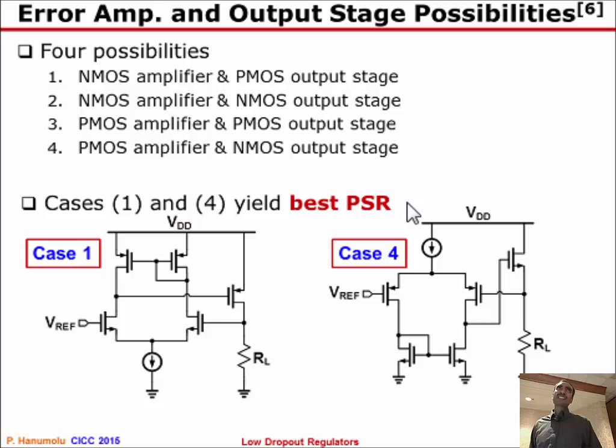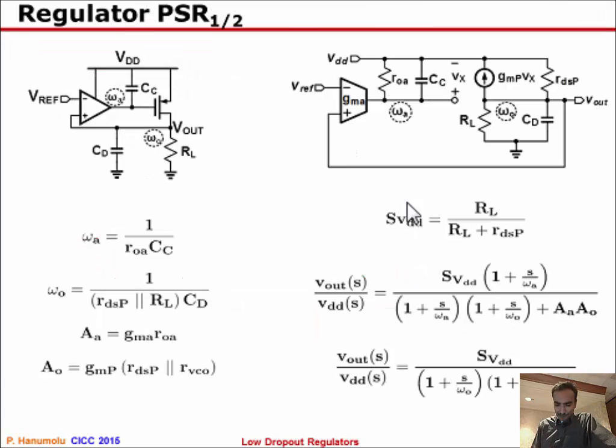Again, the overall PSR actually depends on what kind of output stage you have. NMOS is way better, but unfortunately, you will also have to deal with a very large dropout voltage that comes with an NMOS output stage. Okay.